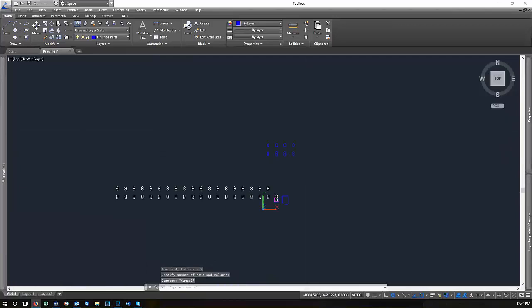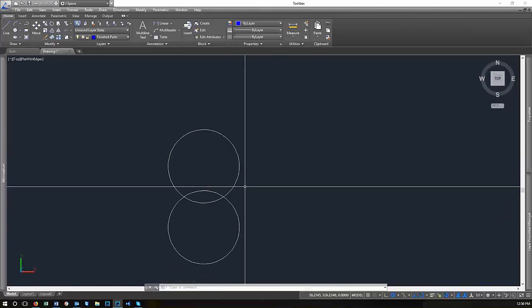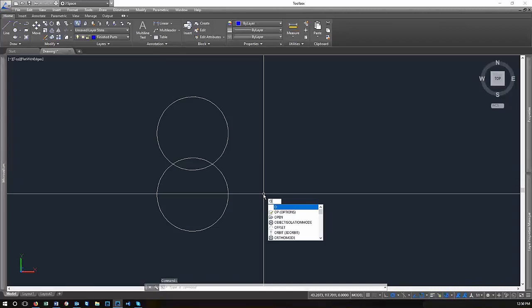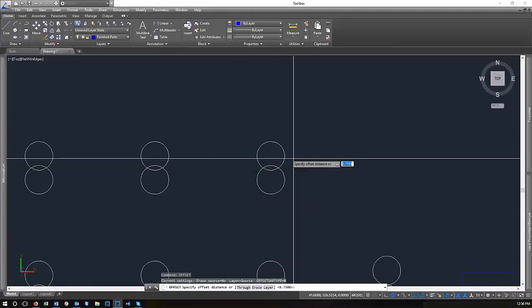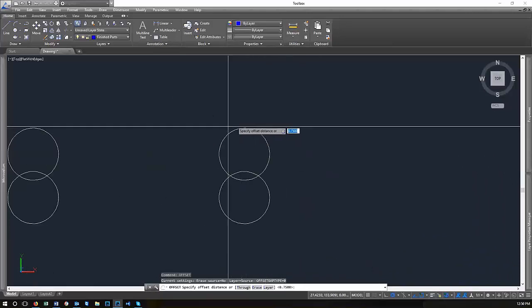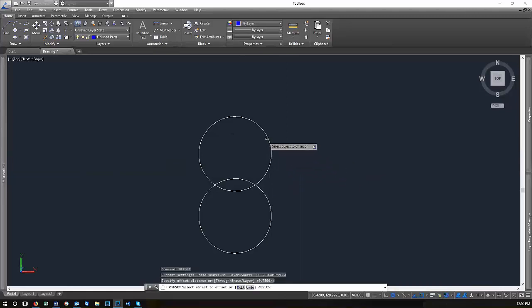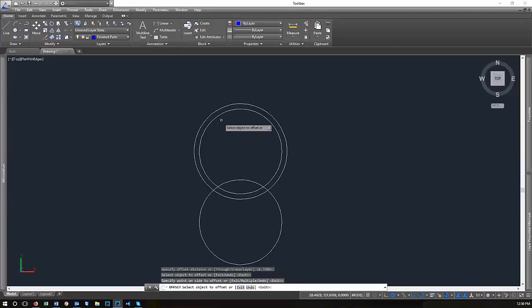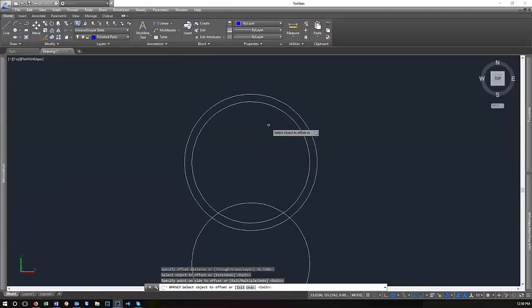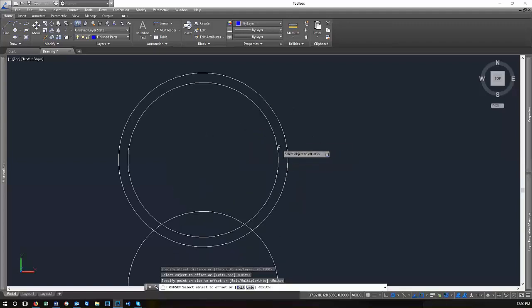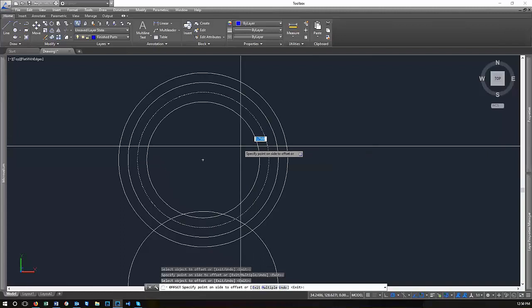Okay, very good. Okay, sounds good. We've also covered the offset command, but just as a review, because we're in that section now, offset is going to create a parallel line to your source object. So I'm going to offset 0.75, and it's going to create another circle 0.75 off of that. So it's great for doing double line prints for like house plans, or for creating thicknesses of cabinetry parts. And you can continue doing that as many times as you need.